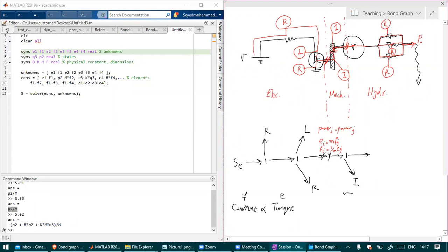So here is basically, I'm going to identify it later, but this part is DC motor, this part is gear 1. So we know the velocity of gear 1 and the velocity of gear 2 are related, right? Velocity of 1 is equal to modulation multiplied by velocity of 2. So here we need to use a transformer, because the flow on one side is equal modulated to the flow on the other side.